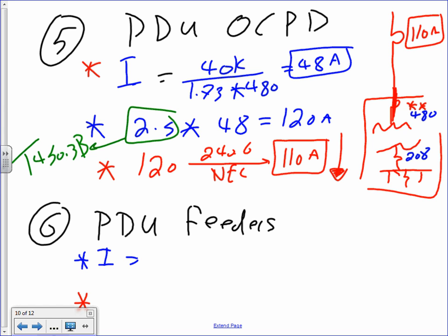No, they either have two hots and put them across the server and run them at 208, or the computers are running at 208 volts. Yes, they convert it to DC, but they take power at 208. Yeah, they have servers that run at 208, single phase though, 2 hots, or 120. But either way, in this case, if it runs at 208, what do you do?